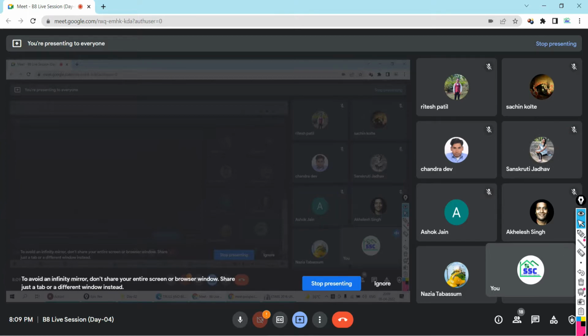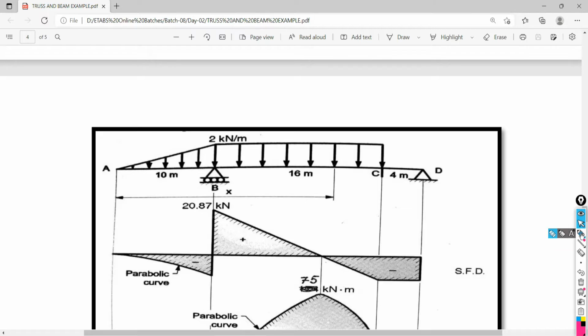Those who said 3, they are right. Actually, see, 1, 2, and 3 that we have to take. Why? Because for assigning of loads, if you don't have a joint, it's okay, no issue. You can assign the point load over the frame. But for assigning the support, there is no option except to have the joint. So anyhow you need to have the joint.